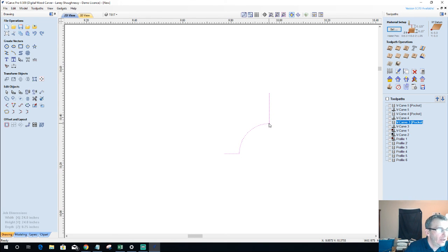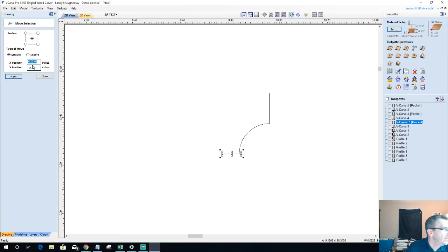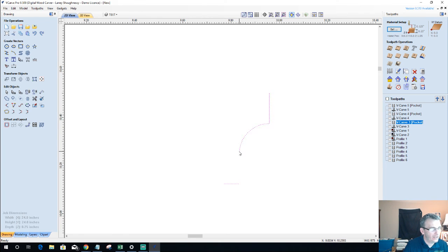Now, from the top of the curve to the bottom of the cutter, it's 1/4 inch. Now this is only an 1/8 of an inch, so I need to go into node editing mode because you have to draw these bits to scale. I'm going to cut the vector there, and I'm going to move this line relative to its position on the Y. Up and down is Y. I'm going to go negative down 0.125, an 1/8 of an inch. Okay. And then I'm going to select this vector here, and I'm going to join it with a straight line. Now you can see my router bit taking shape.